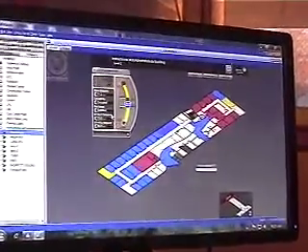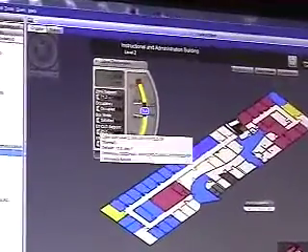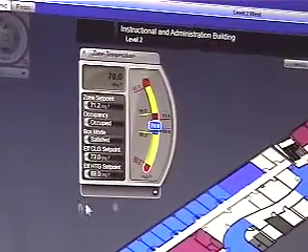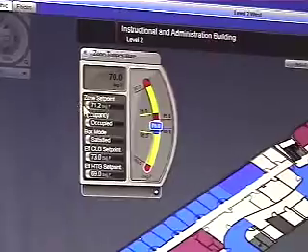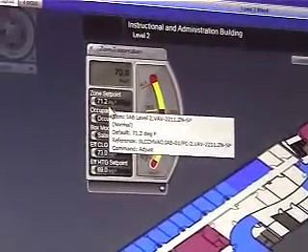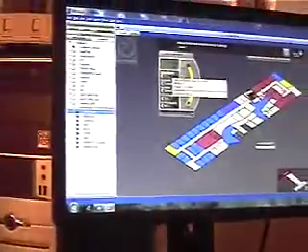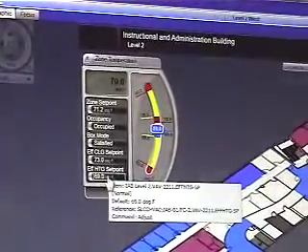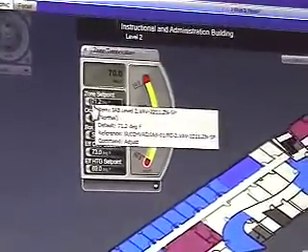A quick thing to note when you're looking at one of these boxes is when you're looking at a zone, it's real important that you're looking at the effective cooling and effective heating set points when you determine if there's something actually wrong. The way that the zone set point works is that it takes this right here. You guys familiar? We talked about this already? A little bit. Yeah. So the zone set point is what's indicated on the dial. There's a 4-degree dead band in between these two. So it's going to take 2 away from the below and add 2 to it. So here you're going to be, what, 69 and 73, which is what the effective cooling set point is. So as long as I'm in this, I'm actually satisfied. Your first glance, you look at it, says it's 70 degrees, but your zone set point is 71.